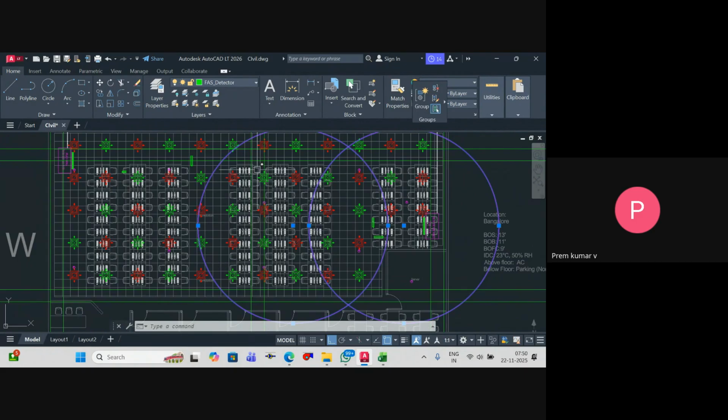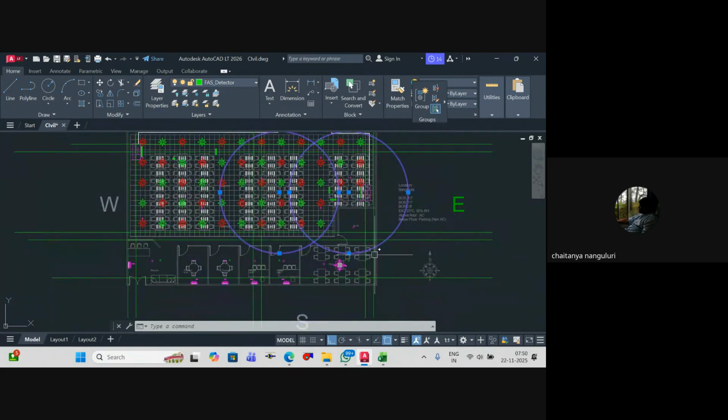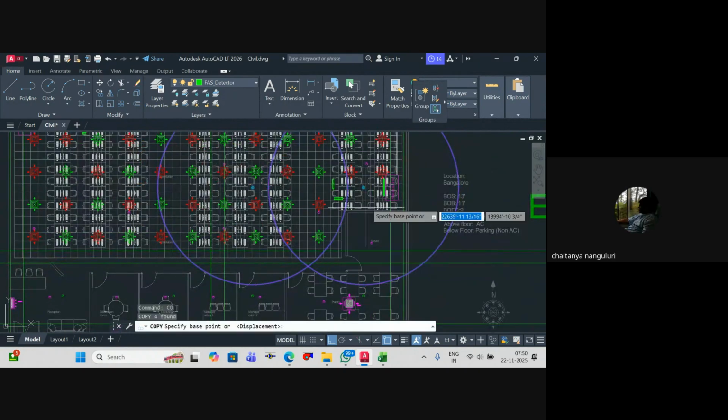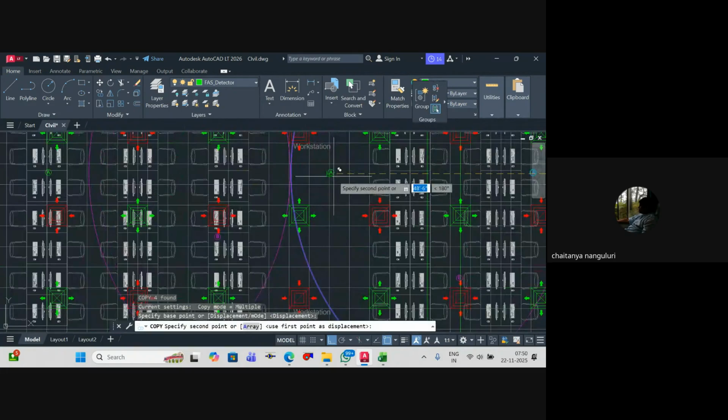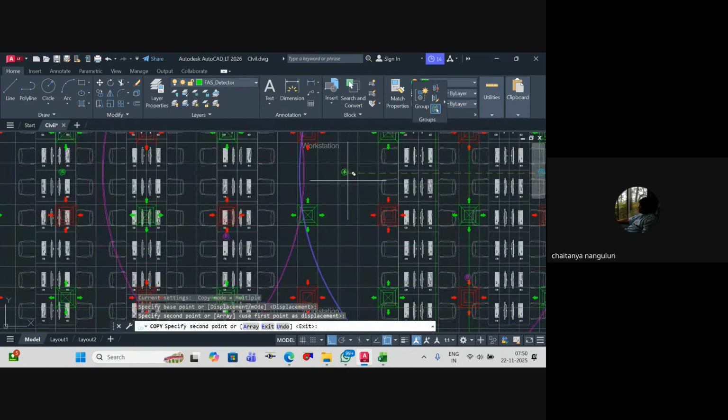After that circle, we have left out even there, right? Yeah, we have, but we can't use it because this beam is an obstruction for me. So only this rectangle is what I have to consider as my isolation chamber, because the beam height is greater than 10%. Got it. So here also we'll place two numbers, which should be sufficient.